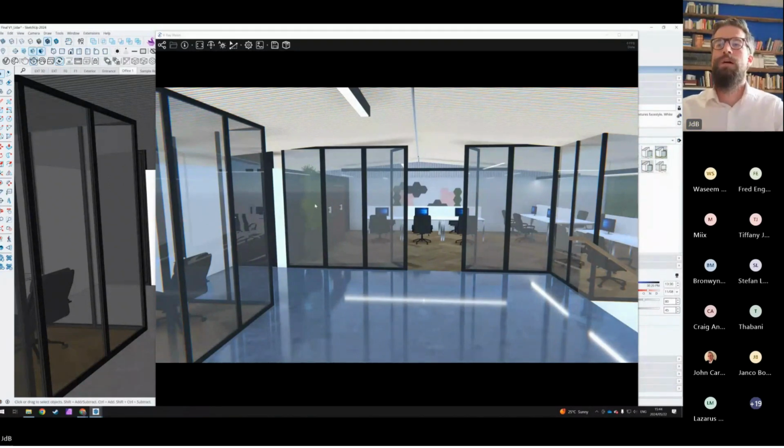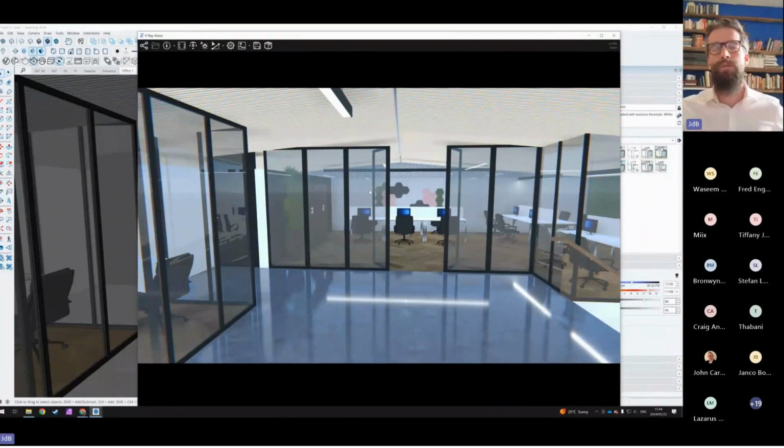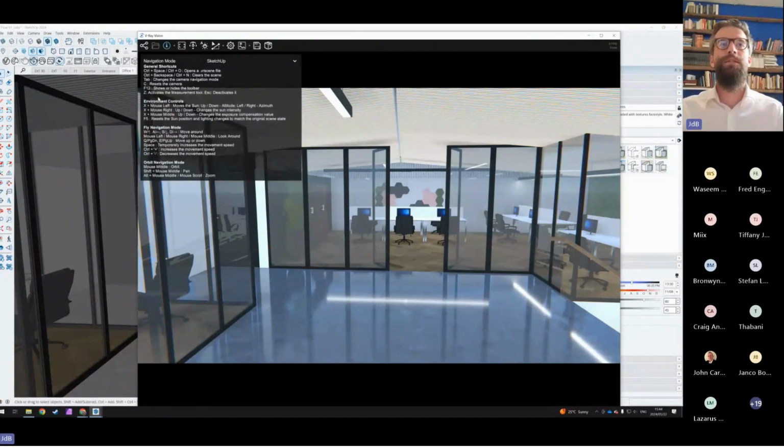For now, I'm going to spend 1 or 2 minutes describing how, even in V-Ray Vision, we can already use some advanced V-Ray rendering tools without having to dive into all the submenus that V-Ray offers. By simply clicking on the information button, there's a little navigation and environment control pop-up. It describes in very short commands what you can do to change the scene. We're going to focus on the environment controls. For example, if we press the letter X and move the mouse up, down, left or right, it affects the position of the sun and its intensity.